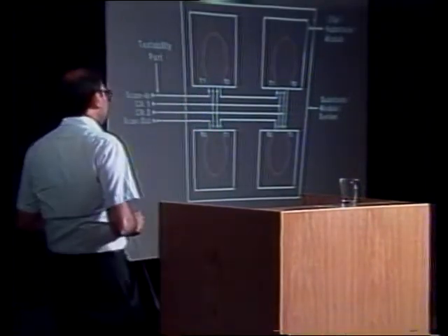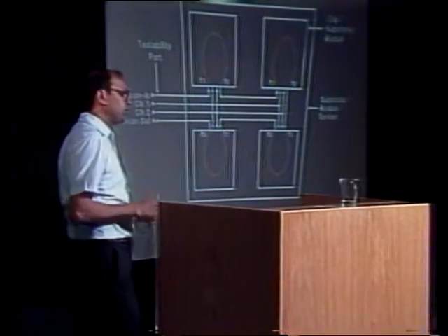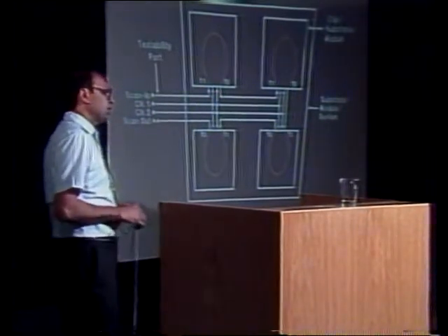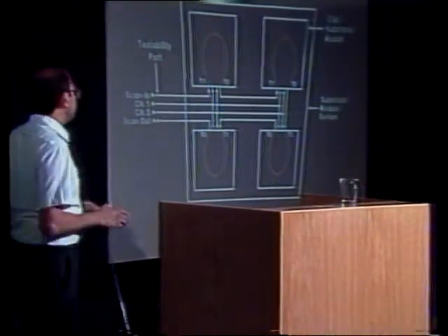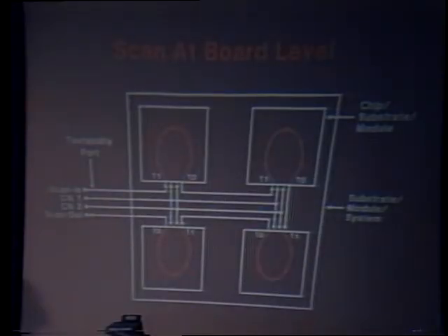Now, the beautiful thing about the linear feedback shift register self-test as well as scan design is that all of them are upward compatible. If you had chips which had scan in them, you could easily pull together all those chain paths at the board level to make it into a board level scan path. And I think the same thing goes for built-in self-test. So this slide just emphasizes that.